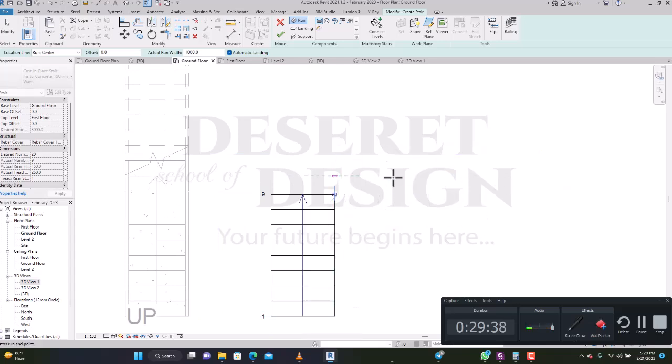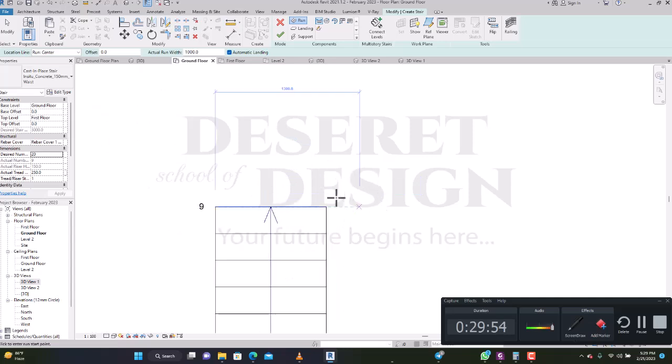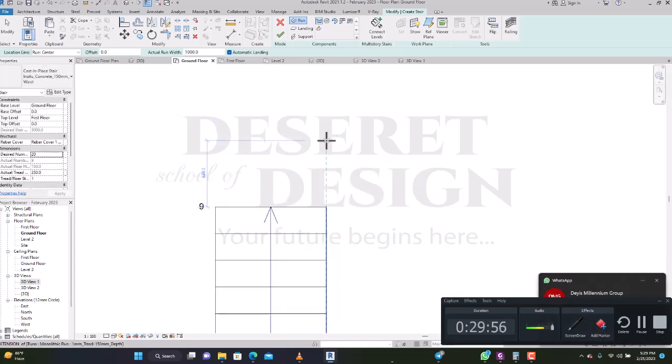No, because the landing cannot be created this way, as even your stair construction is wrong. Sometimes you might not be able to detect the center of the next flight. Since the width is 1000, the middle is supposed to be 500. So I need to determine where the 500 is here, to click before I can draw the next stair.